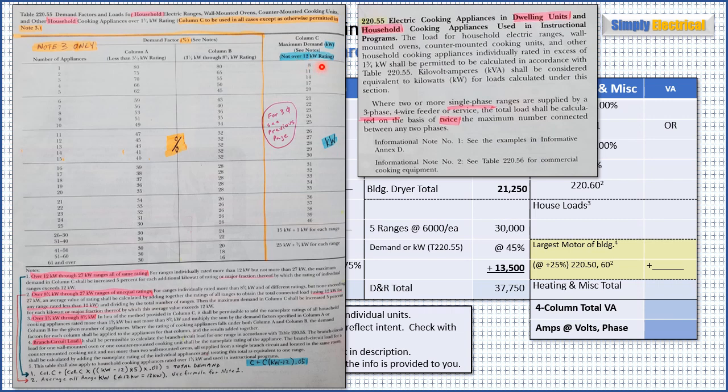They'll be under 12 kW. Not all, there are some larger than that, but most of them are under 12 kW, and so you can use column C very easily. So whatever number of appliances you have, if you have 17, you'll have 32 kW. If you have 25, you'll have 40 kW. If you're going to try to get away with a lower value, then you can use column A or column B if your appliance falls in their respective categories here.